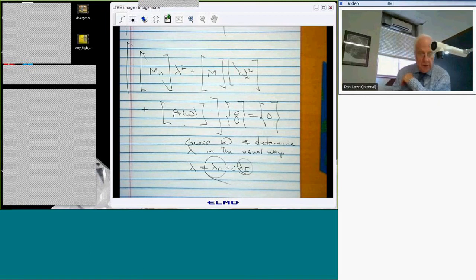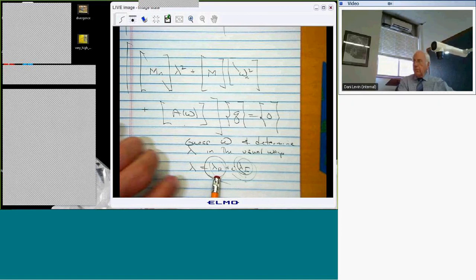So you put those in, and you get the lambdas, and they're not the same, right? But you get a frequency, and of course you get a real part too. What you do is you take this lambda I and use that as your new guess for omega. And then you keep iterating, and most of the time you get where you want to go. Okay. You can actually play this game at any flow velocity, not just the flutter velocity, except that at any other flow velocity, the lambda R will never be 0, right?